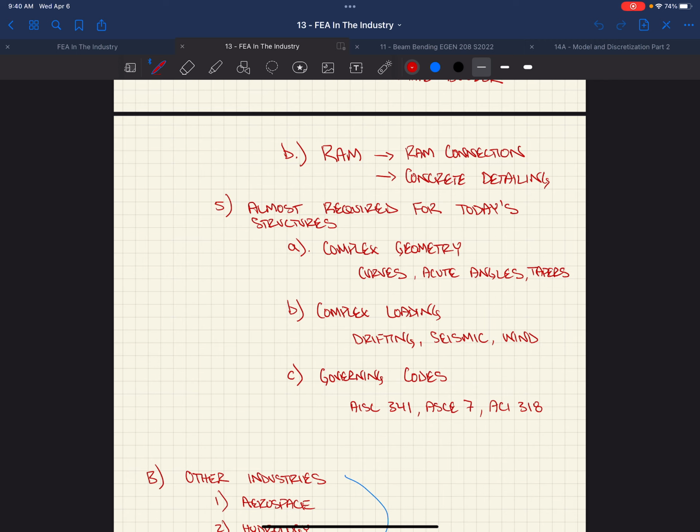But see, if it was a real earthquake and it was close to my loads, then you wouldn't be yielding. Yeah, but you're designing the braces for that earthquake load. Yeah, but then, oh, yeah, okay. And so the braces are what then see that earthquake load, and then beyond that point, they should be yielding, right? They should be starting to dissipate energy. And then from there, what they're saying is that everything else in your system has to be able to handle that brace doing that. Right?